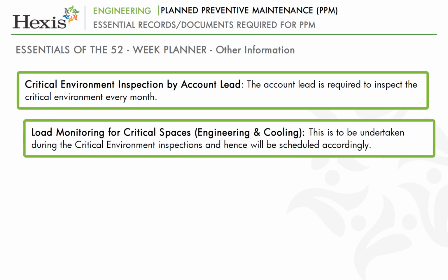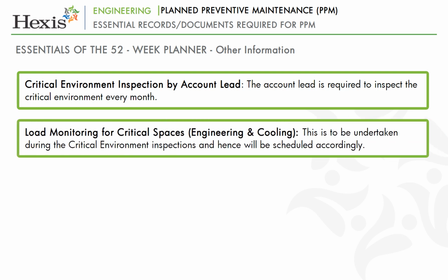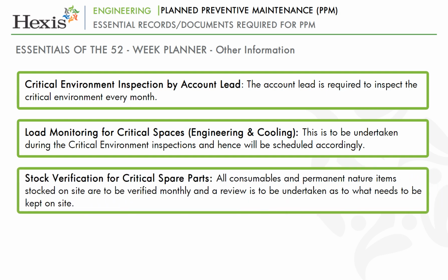Load monitoring for critical spaces, engineering and cooling. This is to be undertaken during the critical environment inspections and hence will be scheduled accordingly. Stock verification for critical spare parts. All consumables and permanent nature items stocked on site are to be verified monthly and a review is to be undertaken as to what needs to be kept on site. The monthly review schedule is to be indicated in the planner.